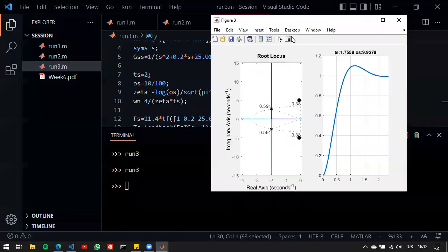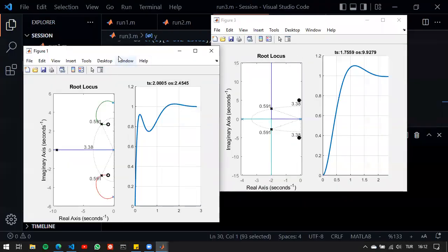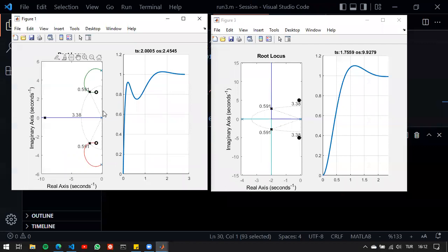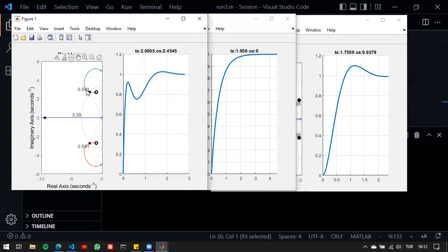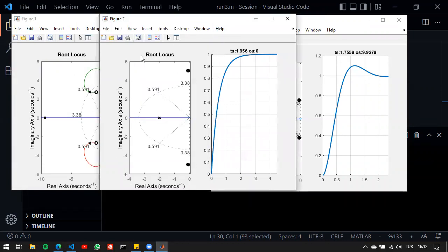So we did learn from the fact that it was not possible to use 2 poles here to get a good result, because we were placing the zeros even more dominantly than they should be. Therefore, we have this interesting behavior, and we decided to change this by getting rid of the poles. So we canceled the poles with the controller zeros, and we added a pole at the origin.